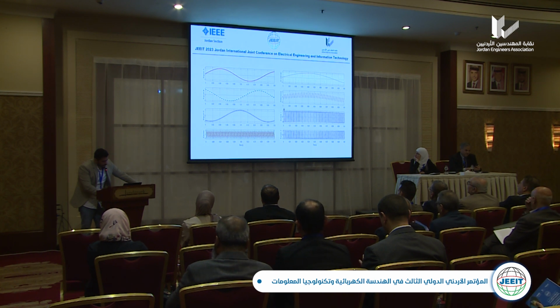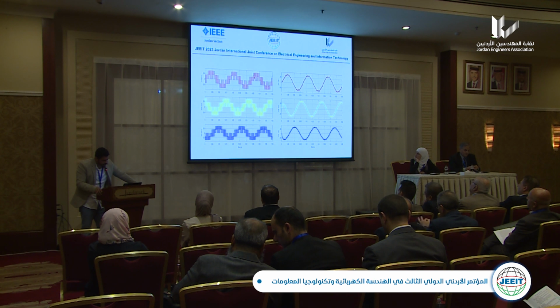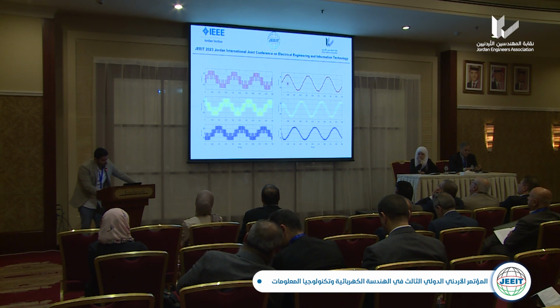We can see that if switch 1 is on, switch 4 will be off in order to avoid a short circuit in the inverter. This is the result for the three-phase inverter. This is the unfiltered voltage signal, and after we enter these signals to the filter, we obtain the three pure sinusoidal wave signals.